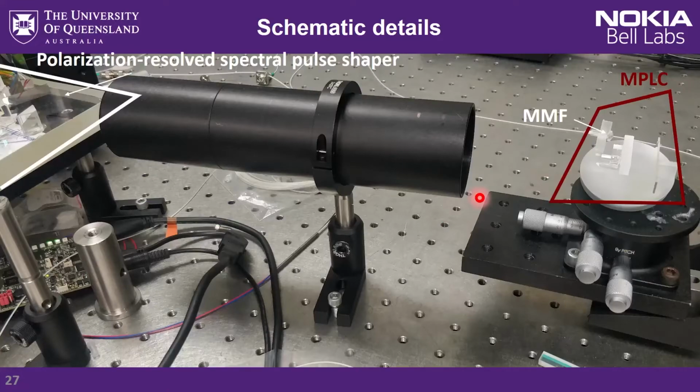So we can now see the MPLC with a side view. We'll see a front view in the next slide. The MPLC is made of a faceplate printed on a substrate and a parallel mirror. The faceplate contains 14 phase masks, regularly spaced, that have been calculated to achieve this 1D to 2D spatial transform. Light bounces 14 times and is then injected into the multimode fiber under study, which will add extra spatial mode coupling. This fiber doesn't add much delay as we are using a telecom grade graded index fiber.